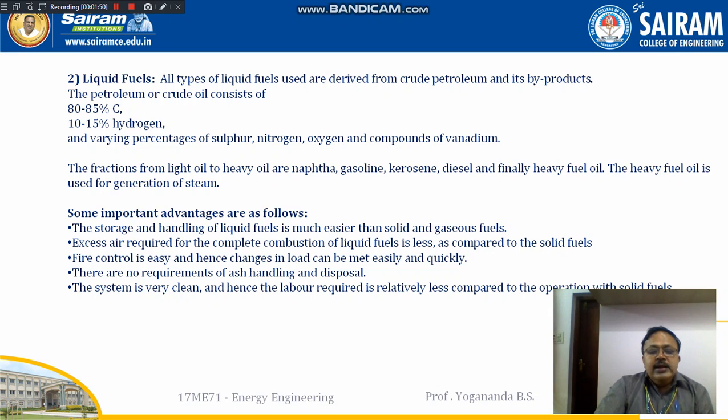The advantage of using liquid fuels will be like this. Handling liquid fuels is much easier compared to solid and gaseous fuels. In the case of solid fuels, complete combustion of the coal is taking place only in the presence of excess air. But for burning this petroleum, not much air is required. The control of fire is also easy in the case of liquid fuels.